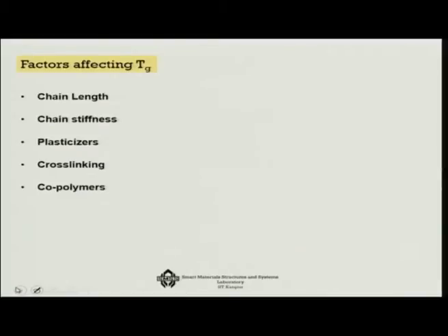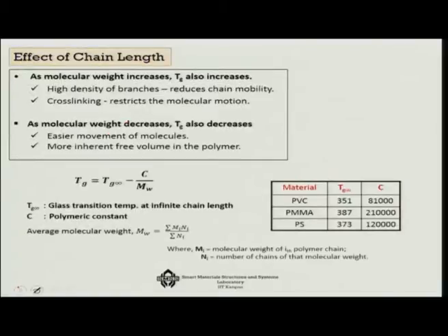What are the factors that affect this glass transition temperature? Well, one is the chain length. The higher the chain length, the more will be this. Chain stiffness, plasticizers, cross-linking and copolymers. Let's look at them one by one.